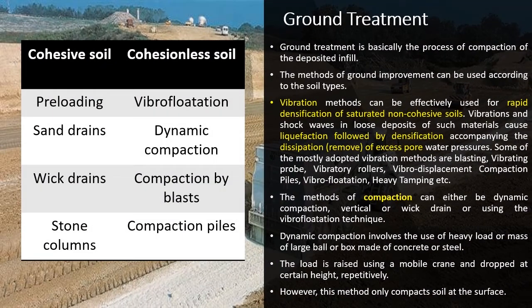Ground treatment is basically the process of compaction of the deposited infill. The method of ground improvement can be used according to the soil types. Vibration methods can effectively be used for rapid densification of saturated non-cohesive soils.